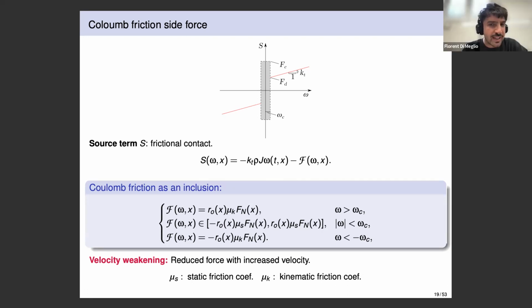Roman, do you have anything to add on that topic? Maybe. Yeah, I think you nailed it on the head. So it's for simplicity of that estimation, because especially if you assume that the red line is flat, so it's horizontal, it's even easier to estimate. With the Stribeck curve, you have several parameters to estimate, plus it's also nonlinear.